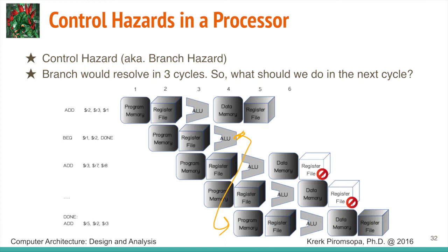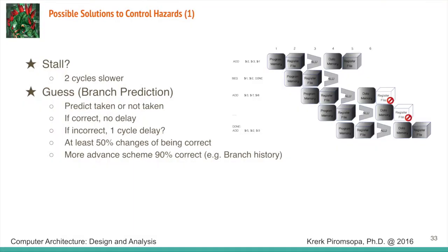So sometimes we just guess. Like in this case, if we guess that it's not a branch, we start these 2. And if it has to branch, you just load the branch after that and ignore the write back. That way, this instruction seems like it never happened, but you wait maybe 2 cycles. So we can wait. If not, we guess.